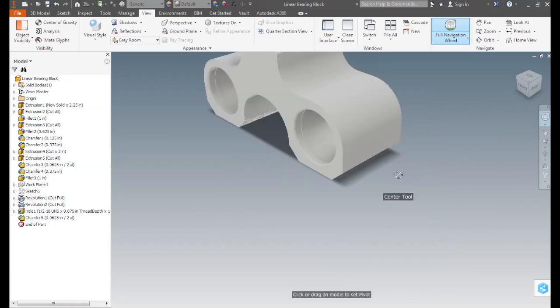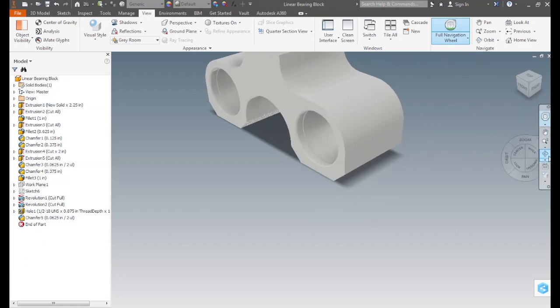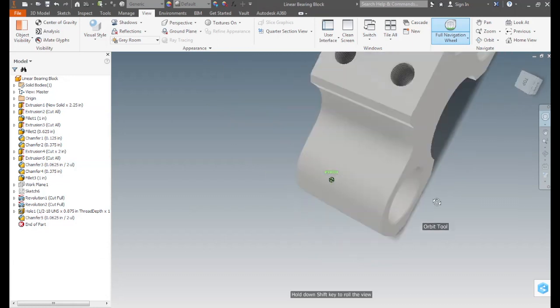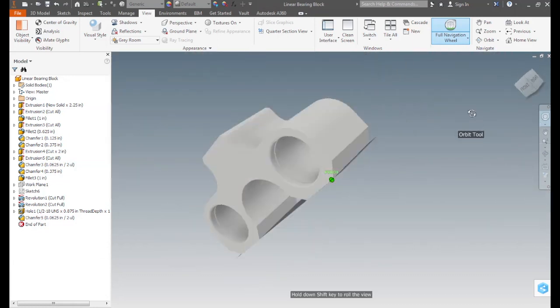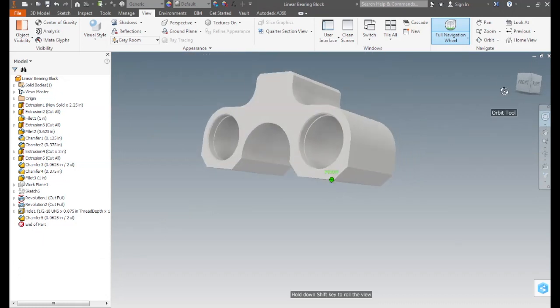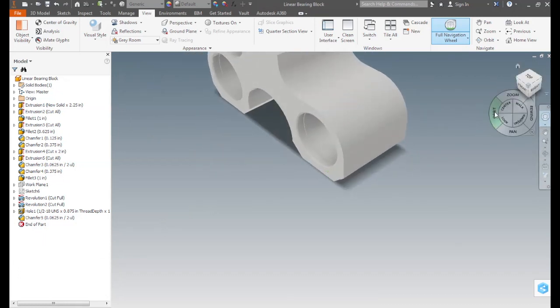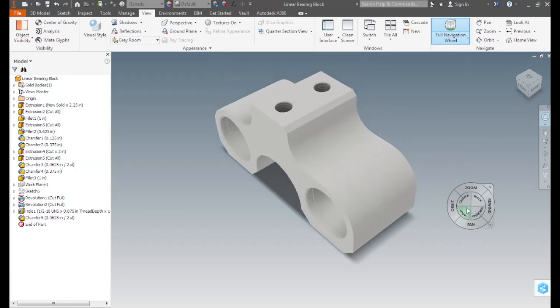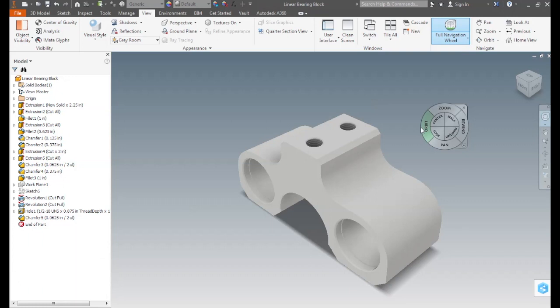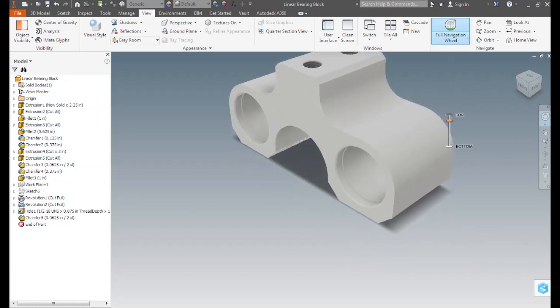Another command on the wheel is Center. Click and hold, select a point. Once the center is selected, it will be the center focus for zooming, and in this case for orbiting. With the Up/Down command, one changes the camera view up and down respectively.